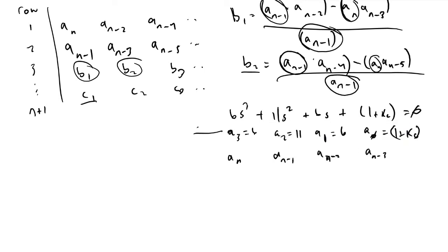So if we take this stuff, plug it in, we'll have row 1, 2, 3, and 4. And we will have a sub n, which was equivalent to 6, a sub n minus 2, which was also equivalent to 6, a sub n minus 4 is equal to 0 because it doesn't exist, and we can continue to pad our Routh array with zeros, like so, if you want.